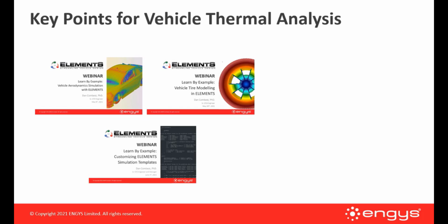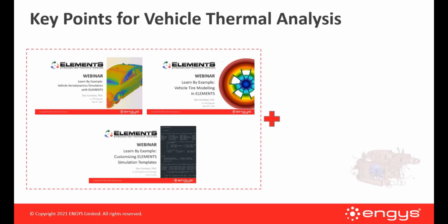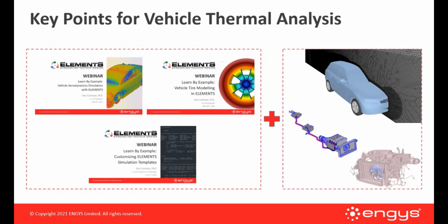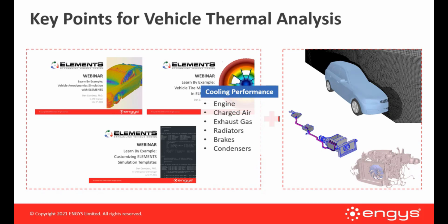All of those combined to certain modeling strategies such as vehicle operation point, whether it's at constant speed or at a soak phase, meshing, thermal libraries, and so on, are key points to what I'm presenting here today and correlate directly to thermal simulations. The flow passing through the vehicle front grills and around its wheels, cooling engine bay compartment, and brake system components is called internal flow, and this internal flow is what directly affects the vehicle cooling performance.